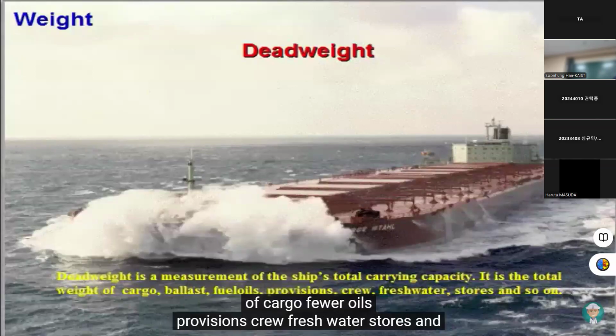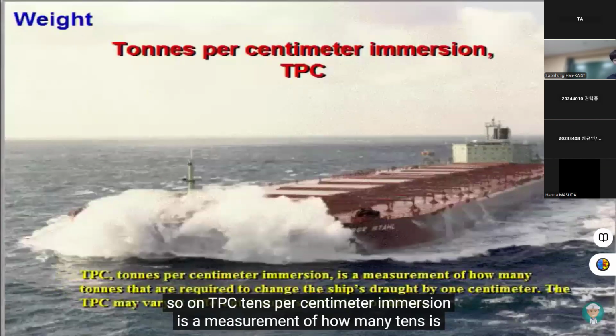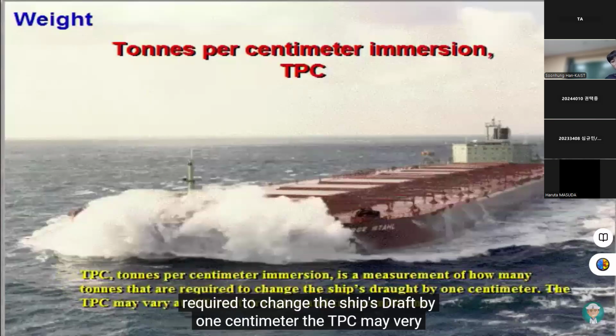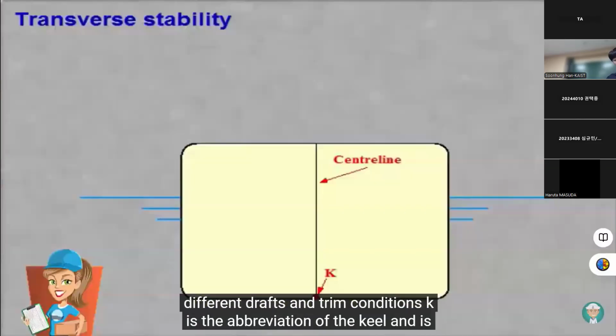It is the total weight of cargo, fuel oils, provisions, crew, fresh water, stores, and so on. TPC, tons per centimetre immersion, is a measurement of how many tons are required to change the ship's draft by 1 centimetre. The TPC may vary at different drafts and trim conditions.